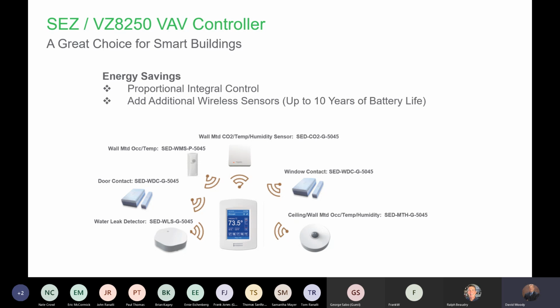But then tomorrow, the customer comes back and says, I'd really like to put this on Wi-Fi and communicate Wi-Fi to my supervisory system. Now you're in a conundrum because there's only one expansion slot, you put the ZigBee radio in that spot, and you have some ZigBee devices out there. You can't add Wi-Fi. We love it, because you're going to have to buy another room controller, and that room controller will have the ZigBee radio embedded on it, which leaves the slot available for your Wi-Fi module.